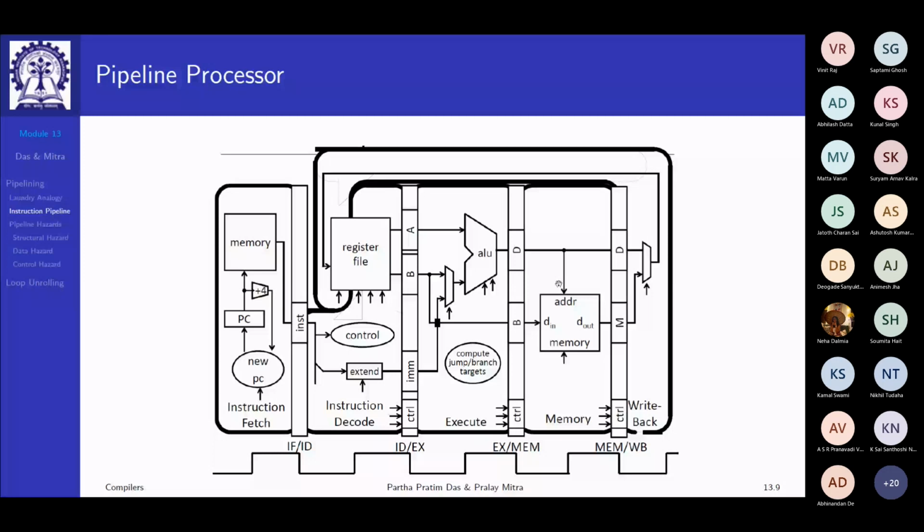And finally, in the write back stage, you have the final memory value or directly the ALU value. For a load, you are taking from the memory and loading to the register, so this path is followed. Whereas if it's an ALU operation, a register type operation, then you directly get it from here.